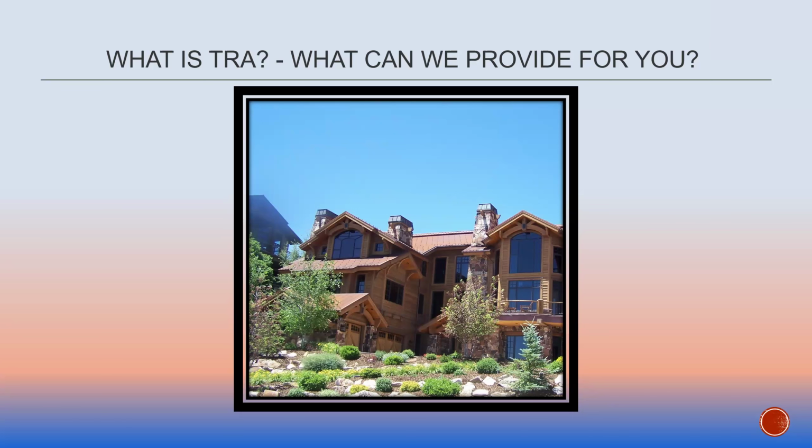Next question: metal roofing systems are usually designed to be fixed at the ridge and side on clips, expanding and contracting at the eave. Do the snow fences clamp to the seam yet still allow metal expansion and contraction? Yes. We clamp to the seam with clamp-on systems for standing seam panels.